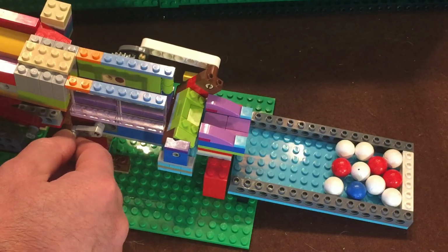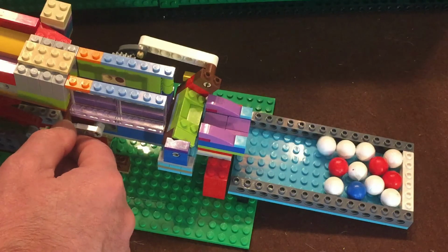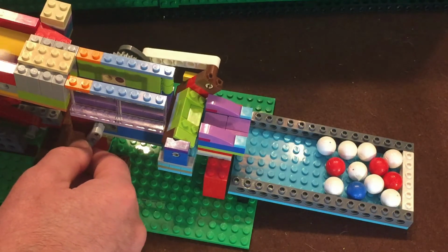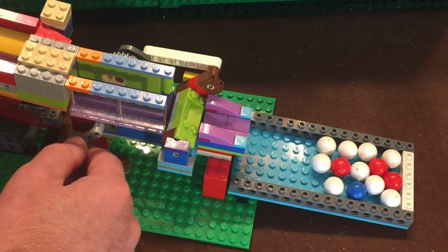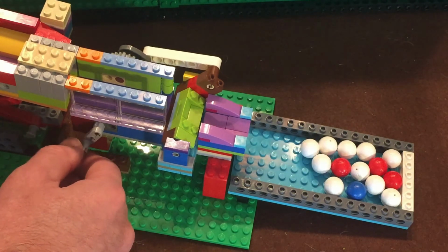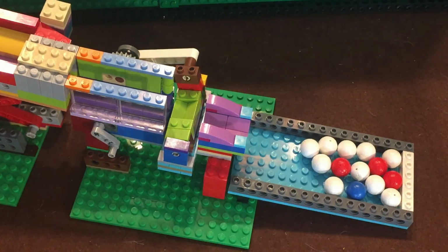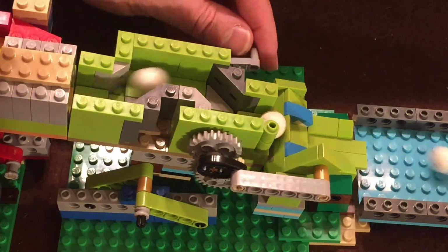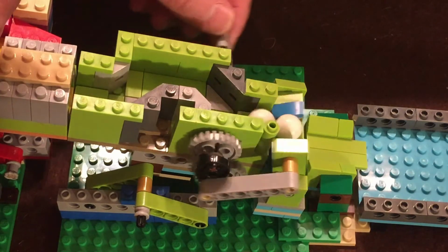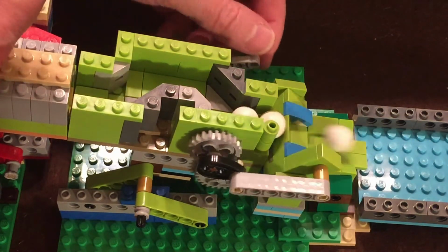Unfortunately, while not prone to jamming, it is susceptible to push. If the balls come in too quickly and the rocker arm is at just the right angle and moving away, they can hit the cradle like a ramp and go right over it. If you're trying to use this for precise timing, that can be a problem. One way around that is to add bends to the input track. That bend will slow down the incoming balls so they don't hit the cradle as fast.